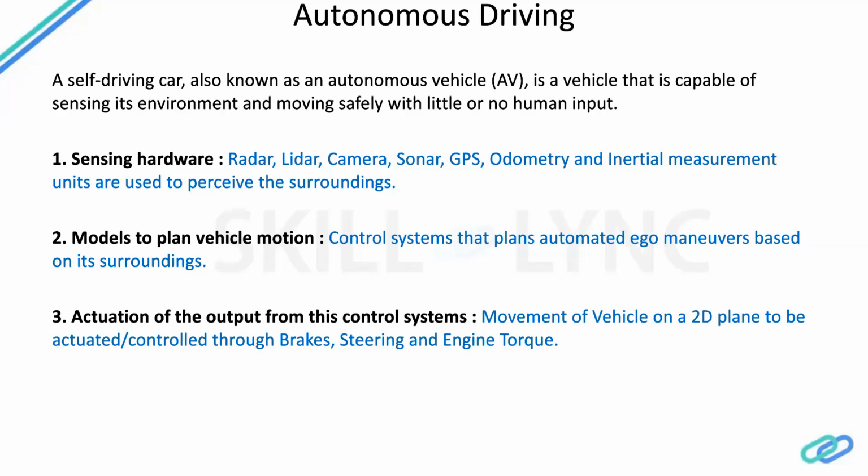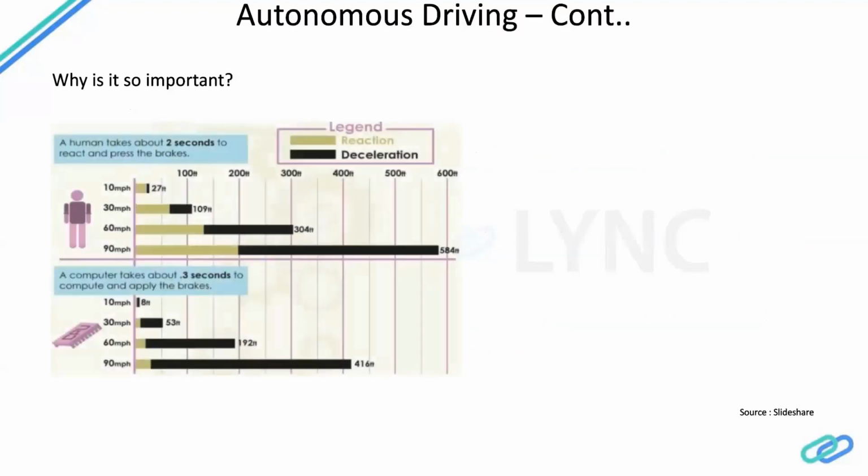Certain kind of things, and then that information will be fed to my actuator lastly. So actuator is nothing but the existing things like brakes, steerings, and the powertrain model for the engine torque requests. So this is the complete closed loop that you see here, from sensing to planning and to actuating based on the environment around my ego vehicle. So let's understand why it is so important.